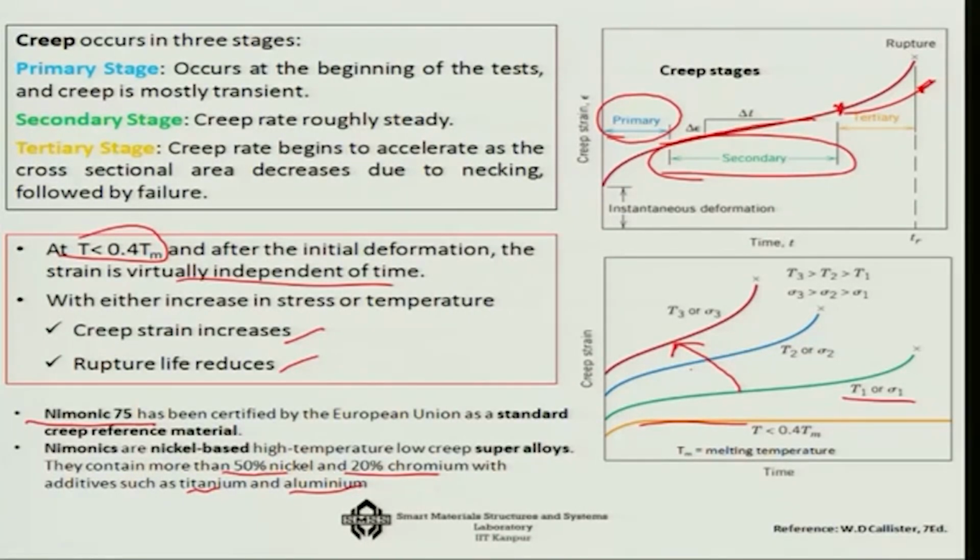And I will not go into the details at this moment, but there are various mechanical models that are actually used. A very common model is a spring and a dashpot combination in series. Okay. And the load is coming here. So, this is a spring K and this is a dashpot. Okay. So, imagine that you are applying a load F and think about how this system will be behaving. That is something that approximately simulates the creep behavior of a system.